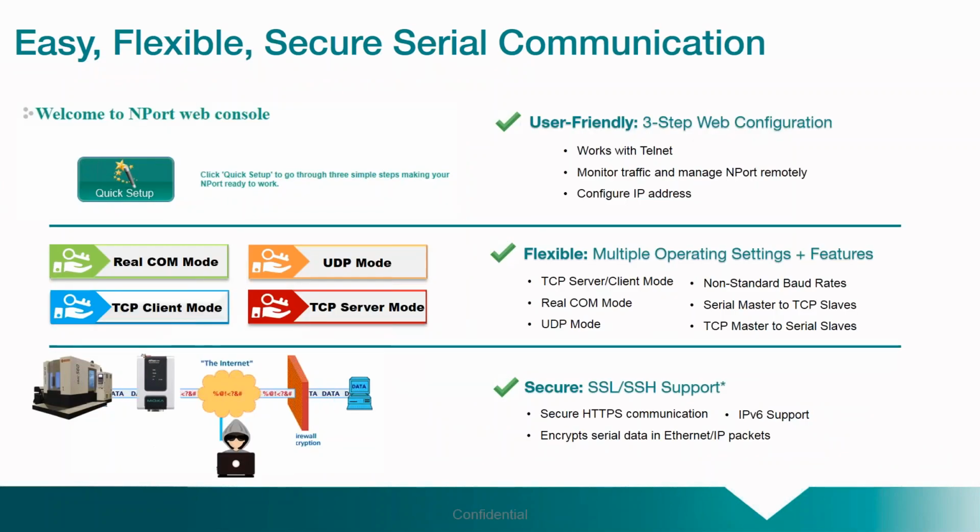So the other thing about the serial devices that we offer here at Moxa is that they come with a very easy to use, friendly 3-step web configuration wizard. It also works with Telnet. It helps you monitor the traffic and manage the port remotely, right? So you connect this to your legacy device instead of having to carry over that cart with that computer to connect to it through a serial port. You can actually connect that and be able to use your computer from anywhere on the network, right? Or even have somebody who remotely connects to your network access that machine now, because you have an IP address.